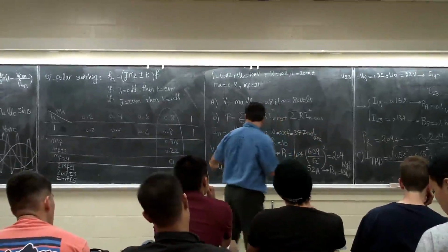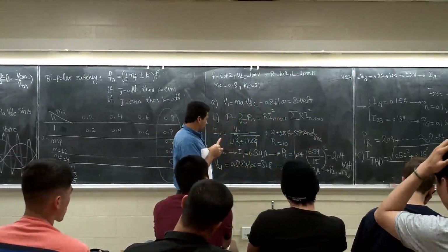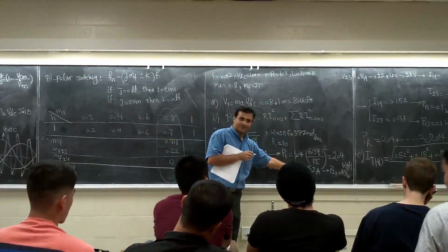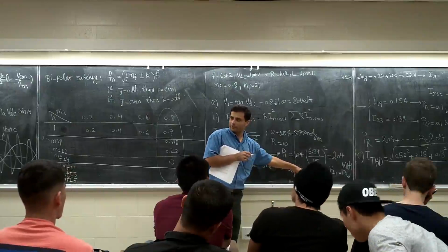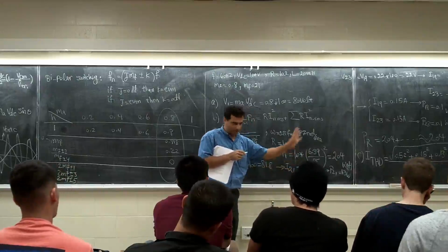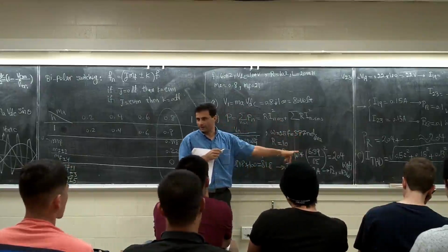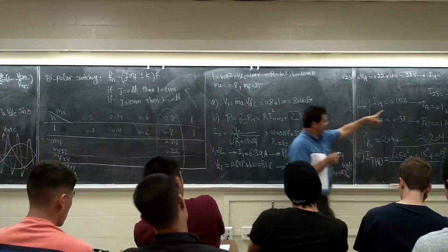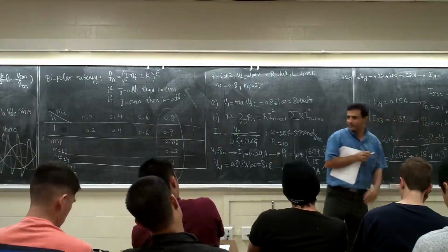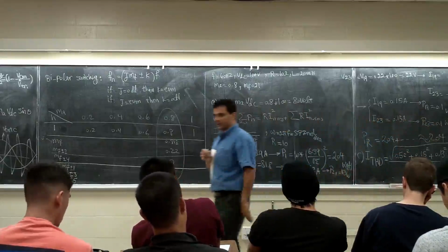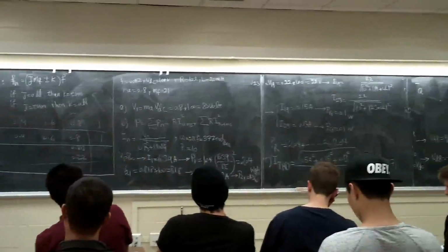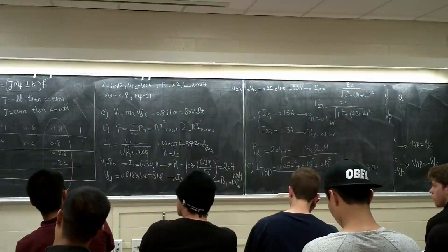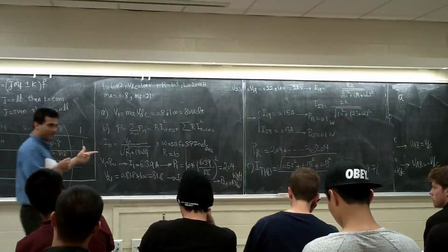But the I-21 is going to become half, right? It becomes 0.25, right? I get rid of the R to be able to linearize it. It's going to be 0.26. And these guys are going to be 0.05 and 0.05, right? So to calculate the THD, maybe it's 4%, I don't know how much. So I'm saying if you increase the MF, your current THD is going to get much better, right?